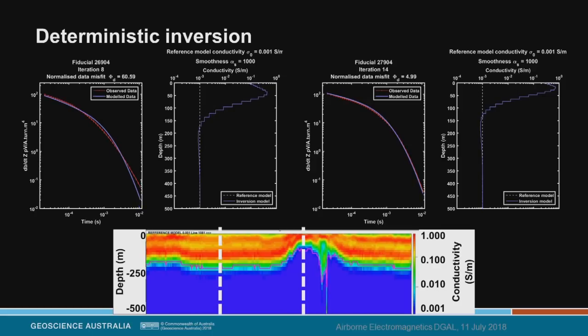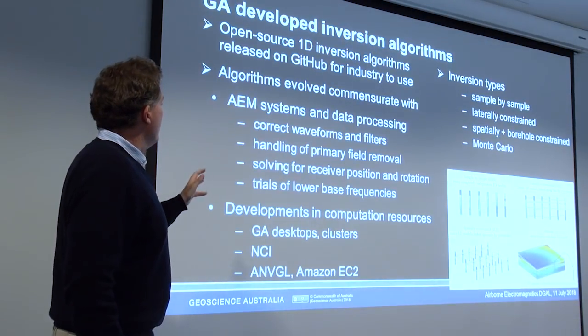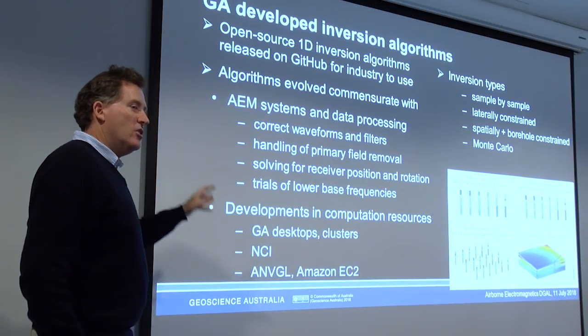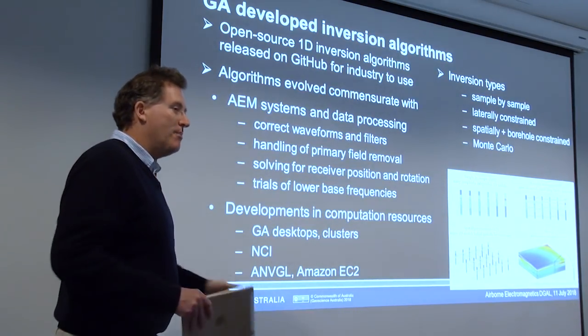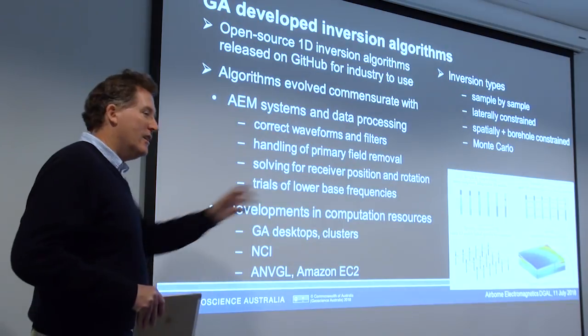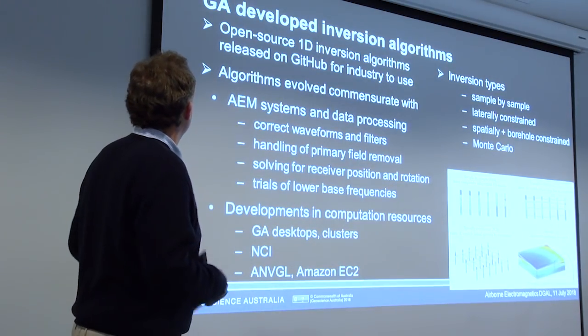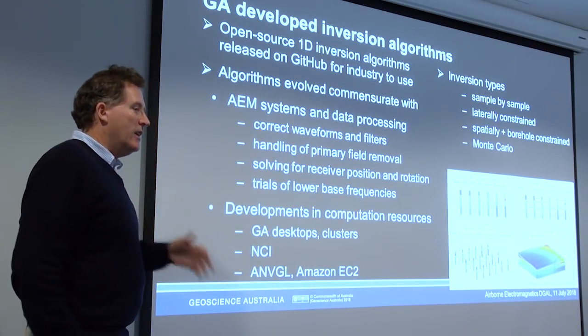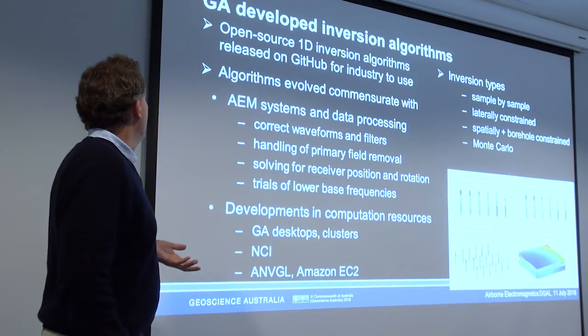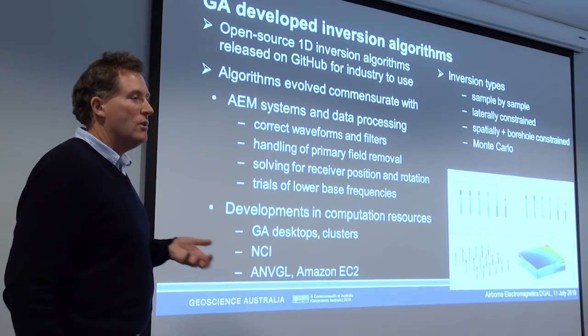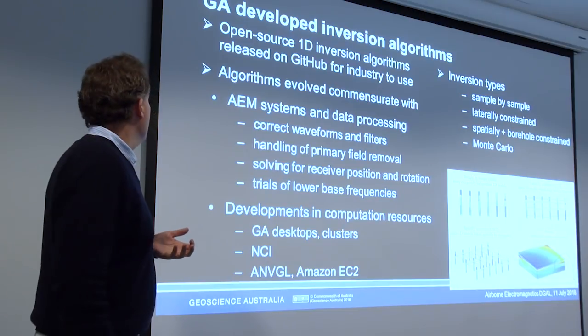So that's basically how our AEM deterministic inversions work, and we invert each of those individual soundings independently and then stitch them all together into sections like you saw at the bottom. So here at GA we've developed several different inversion programs over the years.